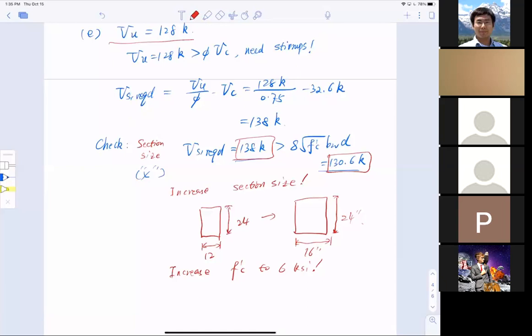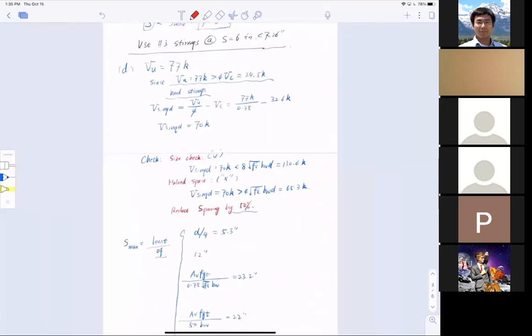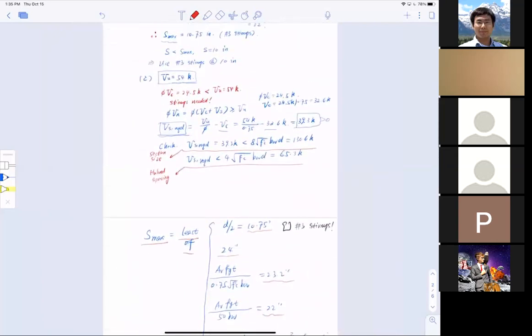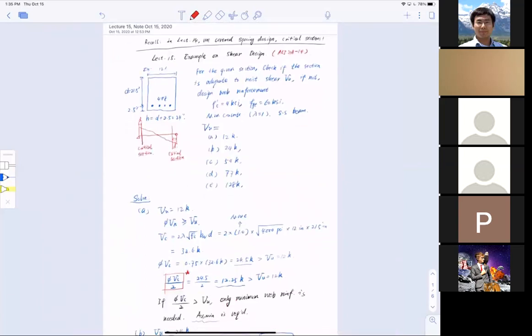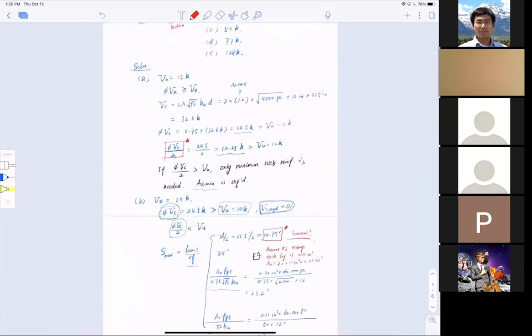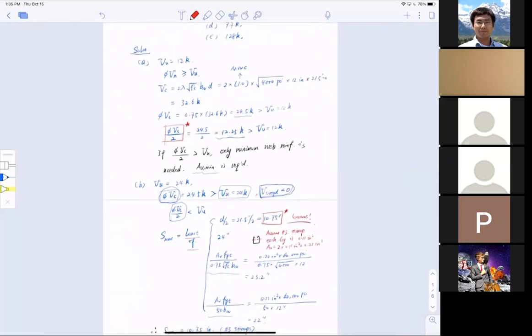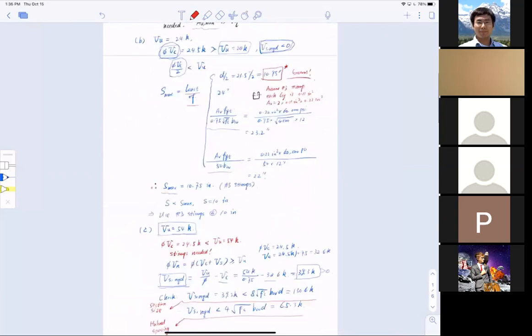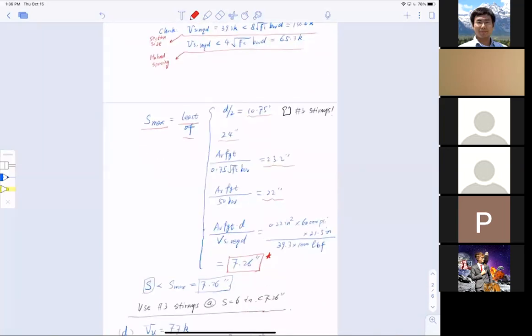So folks, there you go. This is the entire shear design given the Vu. We have varied different numbers. As I increase my shear, in the beginning I don't even need stirrups, just the minimum will suffice. Then I have to use the spacing requirement and find the least spacing. And then I have to calculate it and use the calculated spacing.